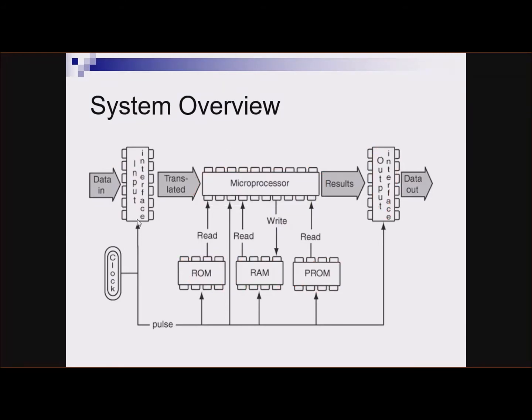So I want to talk about how something might come in and be processed. You've got an accelerator pedal position sensor, which is an analog sensor, possibly or probably a potentiometer. So it's going to have a variable voltage level coming in. As you step on that accelerator pedal, the voltage, with your foot off of it, is maybe 0.5 volt or 1 volt. The voltage pedal to the metal might be about 4.5 volts. And if the pedal's somewhere in between, the voltage is going to be somewhere in between.